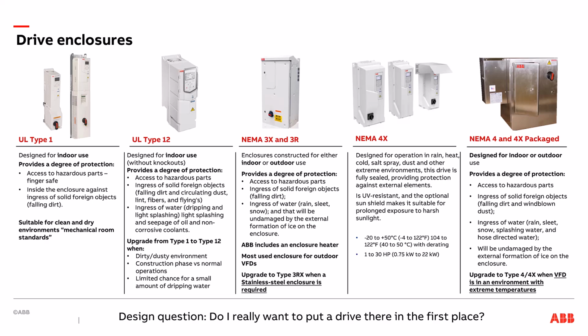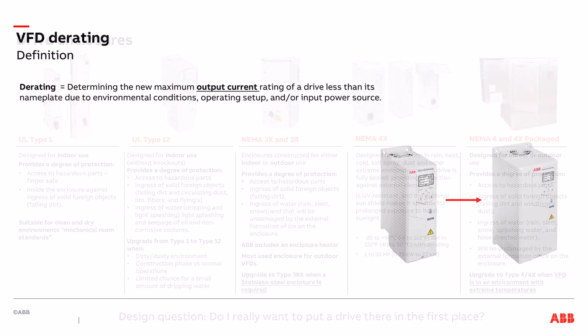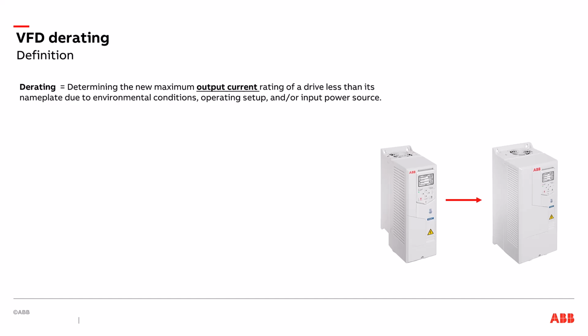These are packaged with a heater and air conditioner, which will mitigate some derate conditions, which we will discuss next. But in each case, remember to evaluate whether or not you really want to put a drive in a location that requires a heater or air conditioner. The drive, if installed and maintained properly, will outlast any air conditioner installed in the enclosure. So let's talk about the topic of derate.